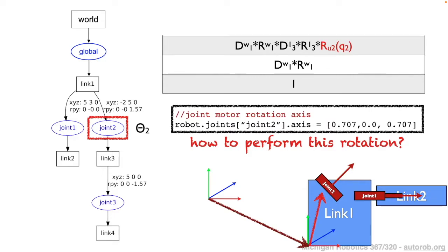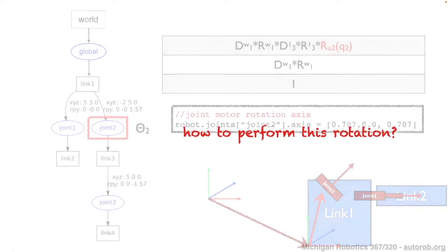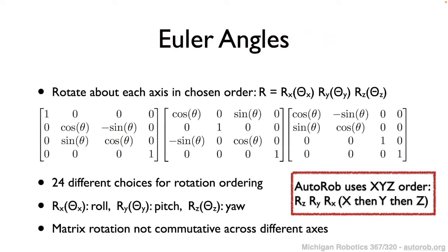Because in the case of translation, we could just define a translation matrix as we had done in the past using our homogeneous definition for translation. But in the case of rotation, it gets a little bit trickier. So now we're going to look at how we might be able to implement this. The first thought is we could potentially use what we used in the case of orienting our joints and links themselves, which was using Euler angles. And that was before we considered the state of the articulations.